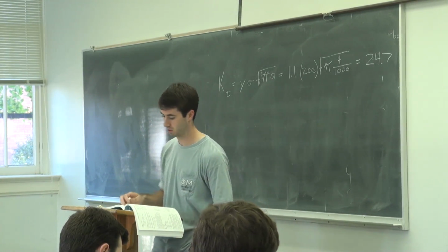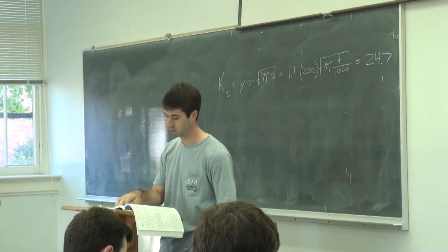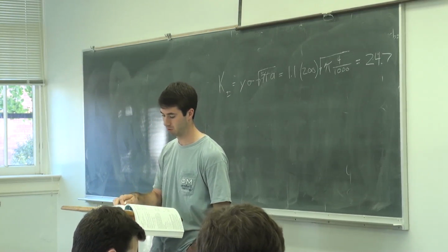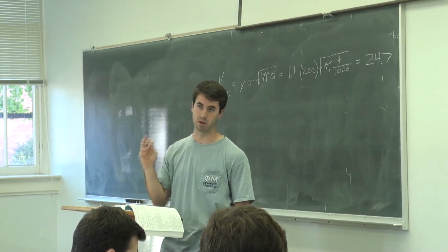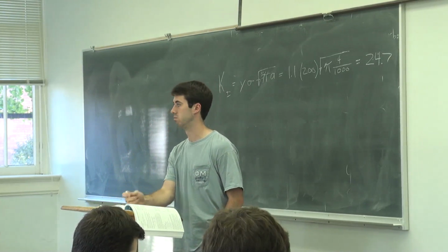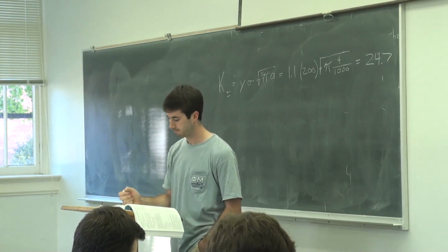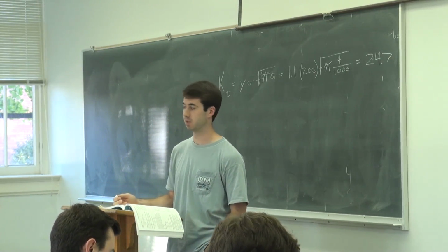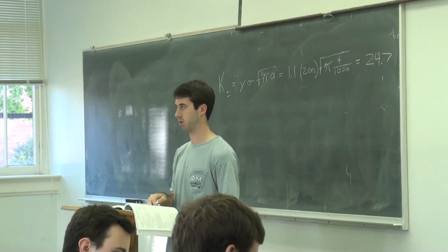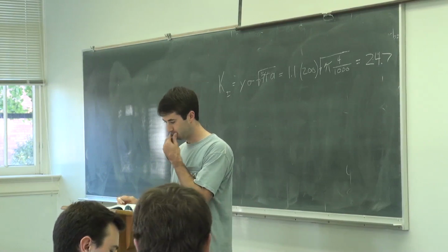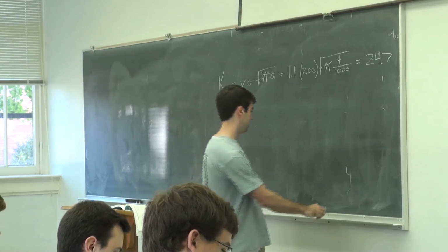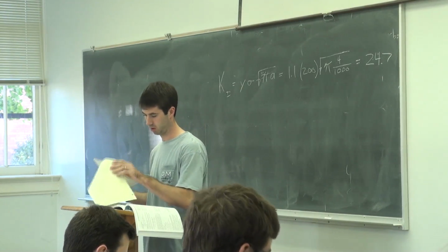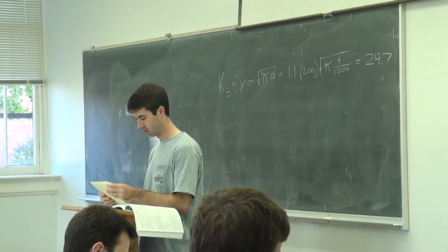So we could use the aluminum 2024-T3 or the 4340 steel. Either one, we got 44 and we got 46. They're both greater than 24.7, so we're good. Does that make sense? So it's a pretty simple problem. It really is just a matter of knowing where to look in this book. All right, take a look at the next page.